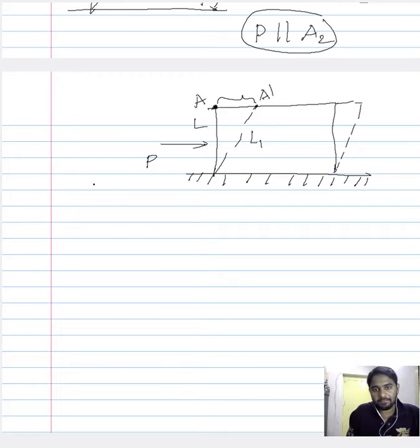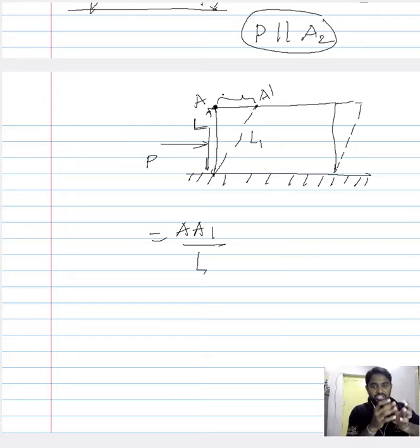Now when you want to quantify this in relation to the original dimension of the material, you do it by this. A1 with respect to this length, from here to here, which we call L, so A1 by L. So if we call this the shift in the position of the corner from A to A1, with respect to the length L, then by taking the ratio of this shift in the corner with respect to the original length, you arrive at what we now call the shear strain.